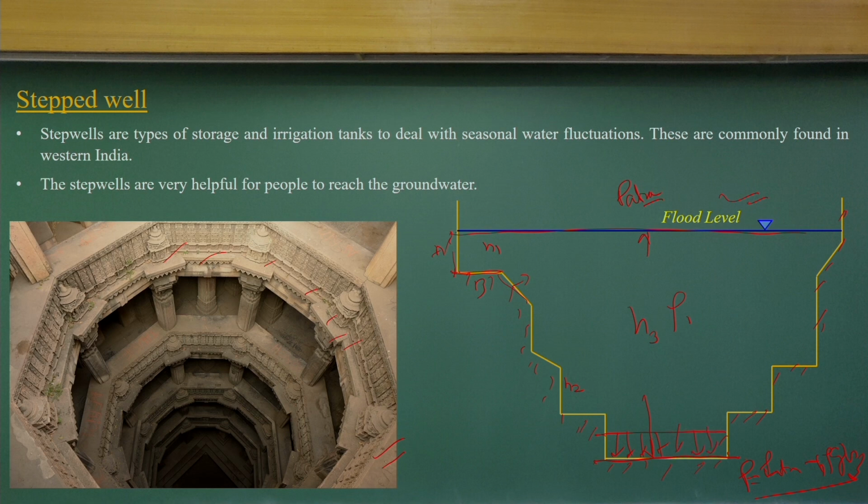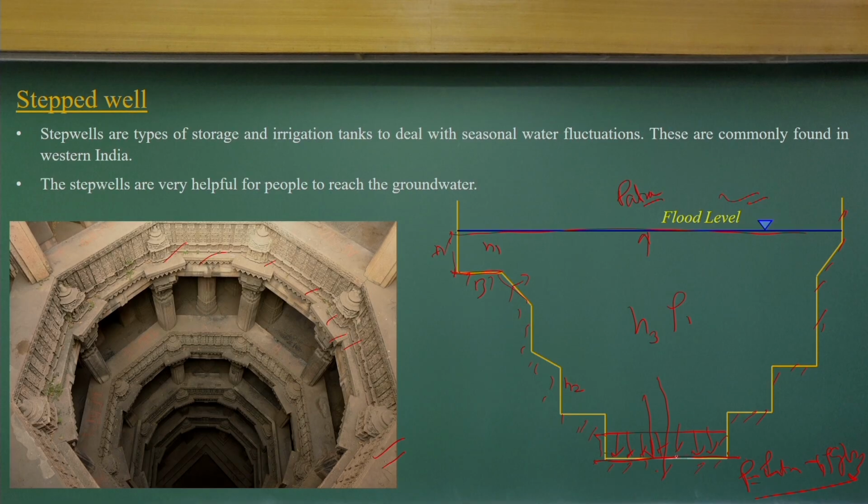As it is a horizontal surface, you will have a pressure distribution which will be uniform. As the pressure distribution is uniform, the maximum force will act at the centroid of this surface. The center of pressure, where the pressure force is acting, will match with the centroid of the surface. The surface can be circular or elliptical in shape, but that is what will act on it. So, you have the pressures of that.